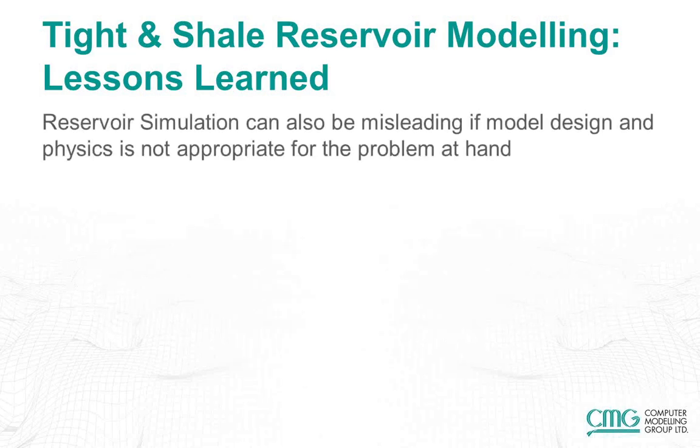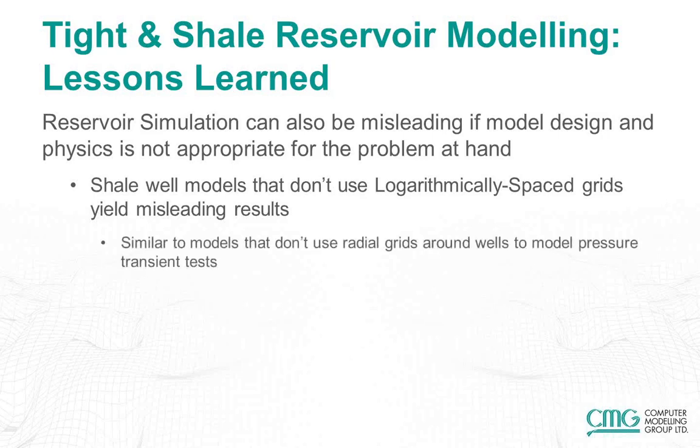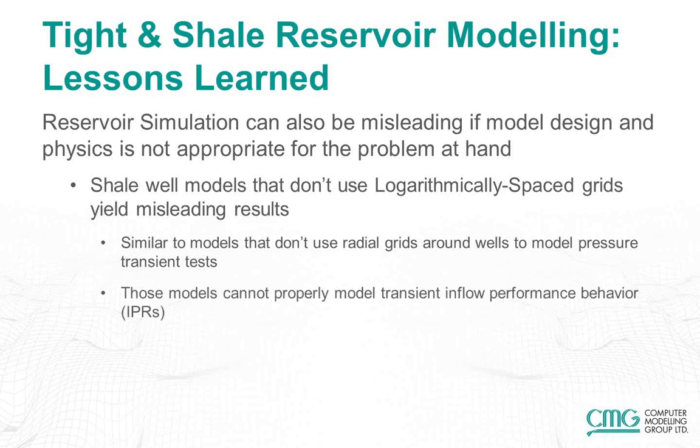And as well, looking at reservoir simulation, depending on the model design, if the physics are not right, it can lead to misleading results. When we are using our builder software, we always add in the logarithmically spaced grids around our fractures. However, if we don't use these logarithmically spaced grids and use larger grid sizes, oftentimes this can lead to misleading results. This is similar to using models that don't use radial grids around wells to model pressure transient tests. These can lead to misleading results since they don't model the transient inflow period. Basically, the assumption is steady state across the grid block.